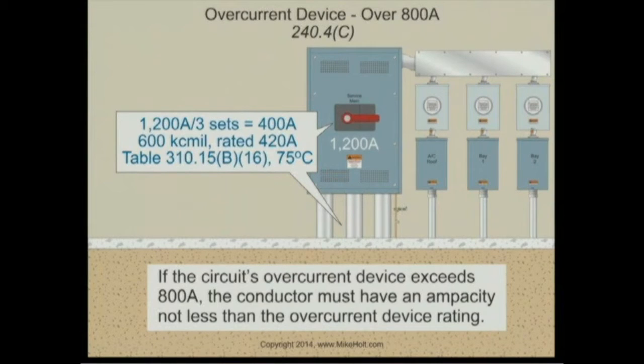Now, Eric, we were just having a conversation this morning. You were saying that you were talking to a cable manufacturer. Was it DLO cable? What kind of cable did they list the wires as MCM? Yeah, it was the cables that are specified in Table 400.5(B), the highly flexible cables, highly stranded Class K, Class M stranding, stuff like that. And as you said earlier, one of these cable manufacturers, they say they do it 90 degrees C free air. I'm calling some of these cable manufacturers, 2 of them actually, and I say, well, I need a price on 500 kcmil. They say, well, we don't have kcmil, we have MCM. Okay, give me a price on 500 MCM.